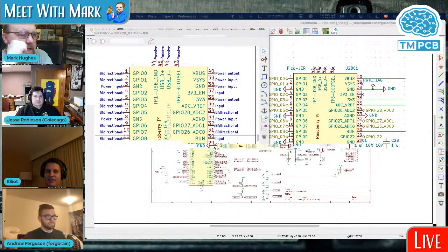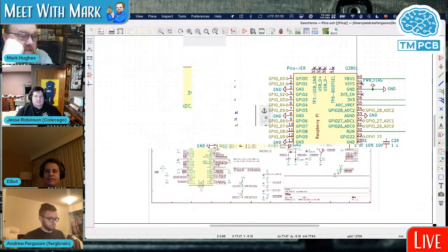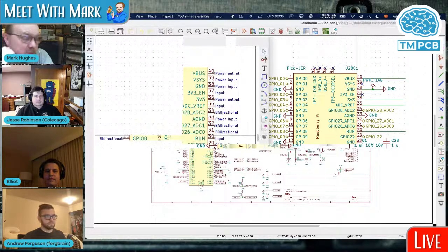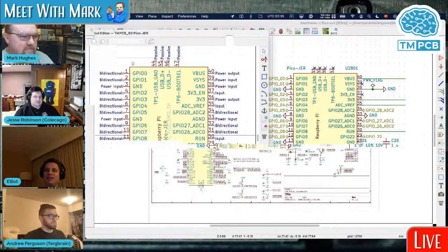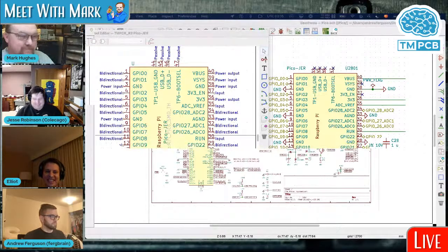Yeah, I'm with Jesse. I don't define pin types, input, output, power, ground. I just leave them all undefined because otherwise it does become quite maddening when you do the ERC. And I've never had it save me. I said I've never had it save me, and it's always annoyed me. My recent experience was I had to troubleshoot what the software was trying to tell me, not a problem with my schematic.